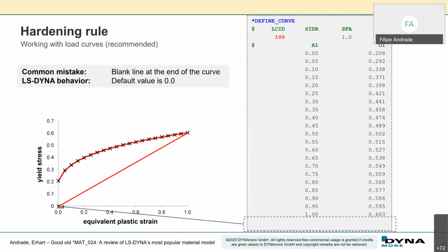So my recommendation when working with curves in include files is you can always use *END at the end of your files, so you can be sure that there's no blank line left in your curves.